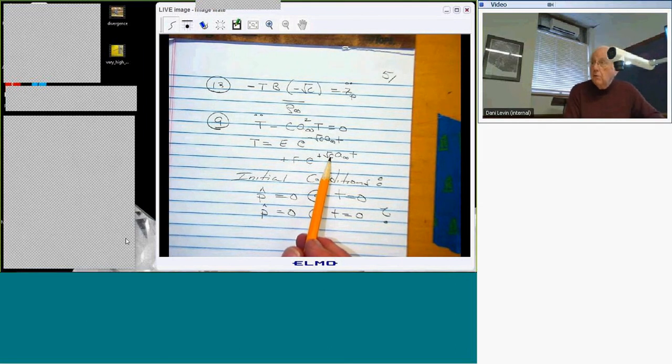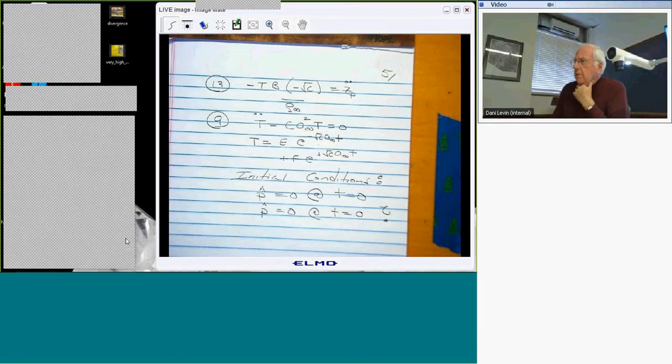I've got a solution. If C is really a positive constant, I've got a solution that's blowing up. And here I got one that's decaying. So if I use the same logic as before, presuming that C is a positive constant, I probably want to throw this one away. But then I think, gee, I'm an aeroelastician. When solutions blow up, I'm fascinated with those solutions, right? Am I throwing away too much? So I think the other thing I would conclude is that C is probably a negative number. And these represent oscillations in time.